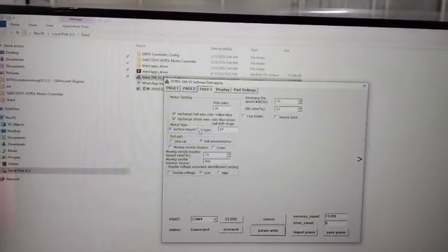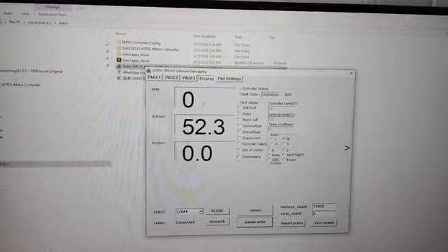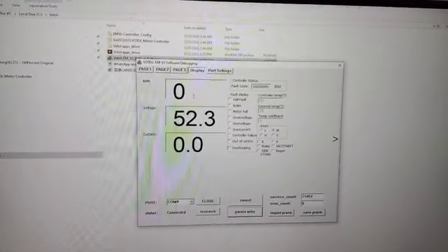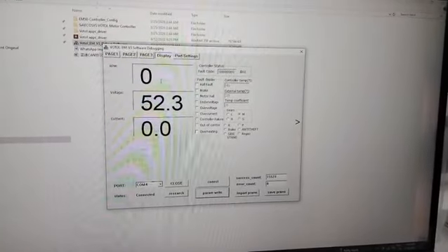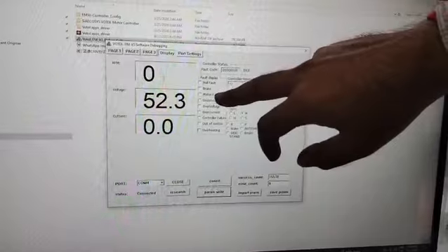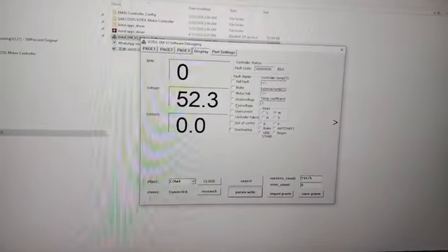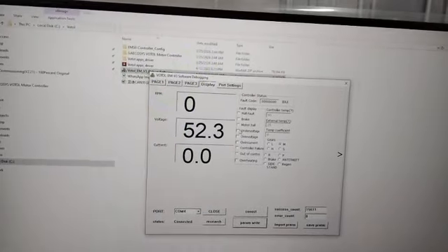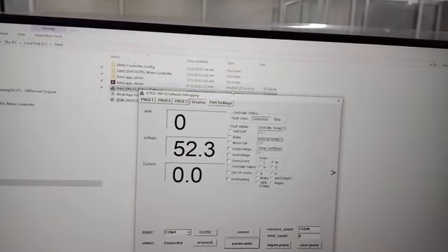On page 3, here is some mounting of this motor we have to operate, and here is a display. Also in this software we capture faults like brake fault, hall fault or hall sensor fault, motor fault, over voltage and under voltage fault, which have a tick mark; whichever fault occurs, we will get it. So thank you.